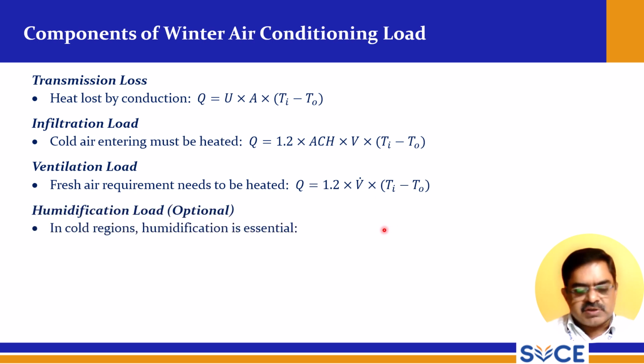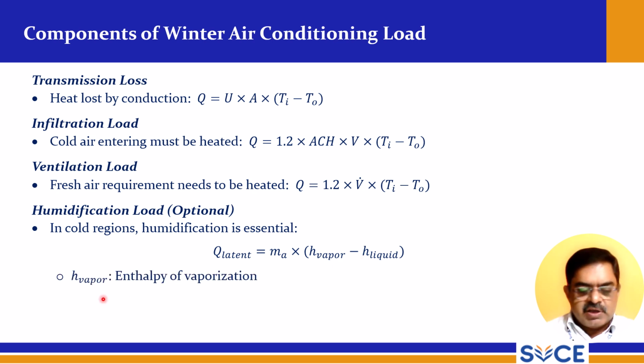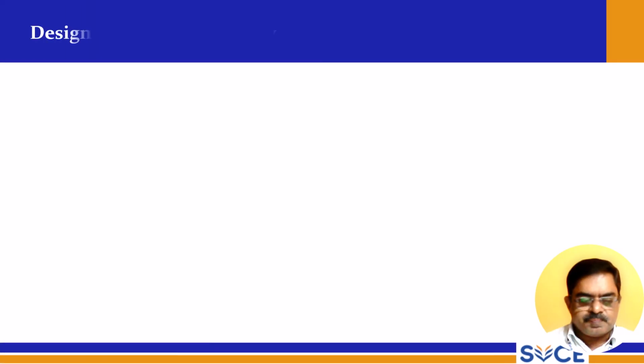Humidification load, it is optional. In cold regions, humidification is essential. So Q latent equal to Ma into (H vapor minus H liquid), where H vapor equal to enthalpy of vaporization, and Ma equal to mass of added water vapor.